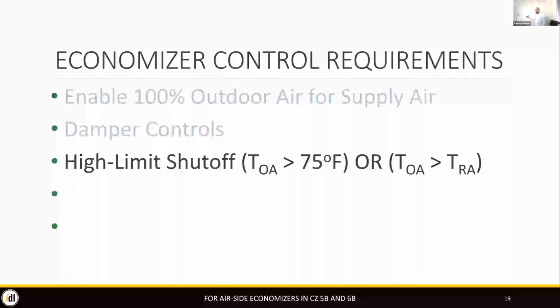So once it starts getting warm, then you start dialing the amount of fresh air back to its normal minimum. Because it's an energy saving measure, right? Because we're recycling a lot of our heat, and if the exhaust air from our building is 73 degrees and outdoors it's 80 degrees, then it doesn't make sense for us to hammer our chiller and bring in all 80-degree air. Let's mix a little bit of it. Unless, of course, you're using a dedicated outdoor air system, in which case you're always bringing in just 100% fresh air all the time. And those are the systems that I really love.